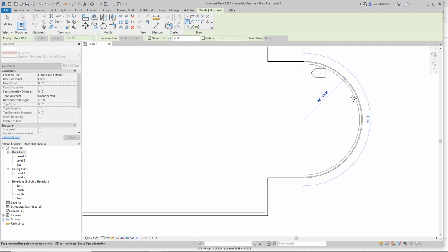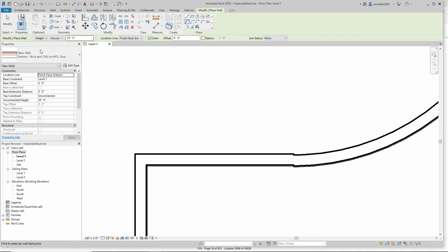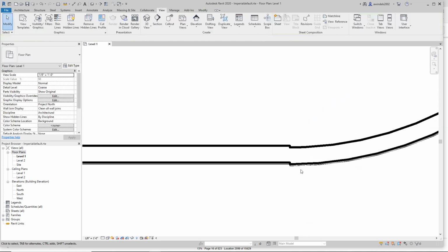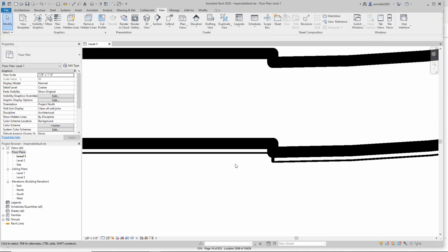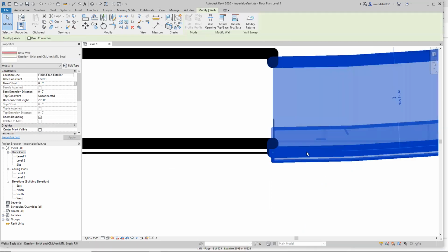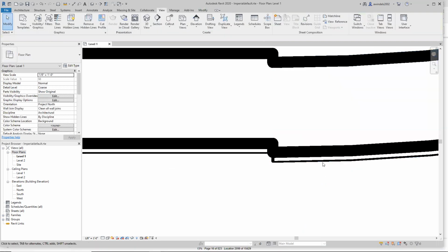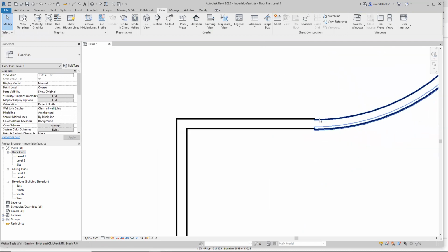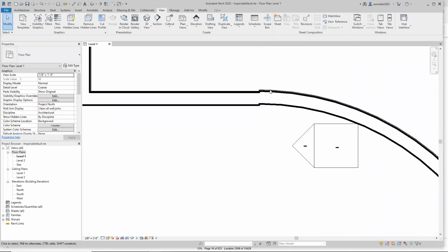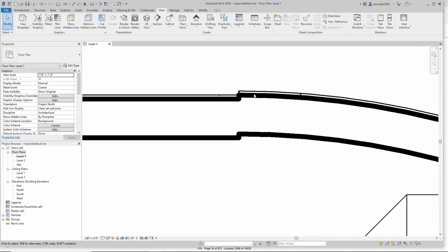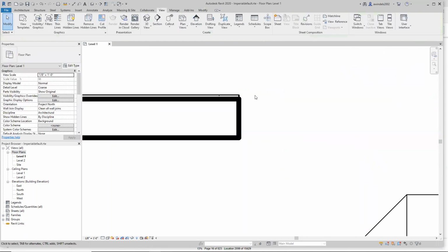So we're going to hold it out there. We'll left click, accept that. We're going to hit escape. Boom. Now, some of you might have a jog like this, and that's okay. I'll show you how to fix that real quick. We'll just pick a different part of the wall because it's easy to snap in the wrong spot. Let's delete it by selecting it. Hit delete real quick.